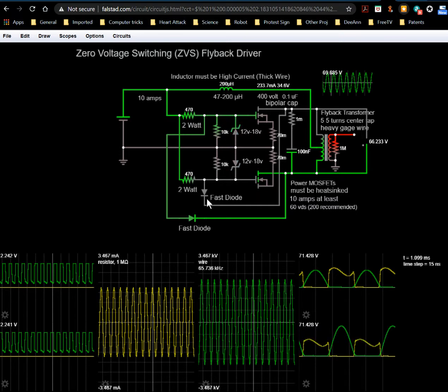Whereas when this transistor's on, this diode's conducting because this becomes very close to ground. So basically, it's siphoning power away from this voltage divider. Basically it's short-circuiting this resistor is what these diodes are doing. This one short-circuits this resistor, this one short-circuits this resistor. It's one of the reasons this resistor is such a high value, so it's easy to short-circuit. So it's not hard to overcome a 10K resistor when you're talking about a diode here.